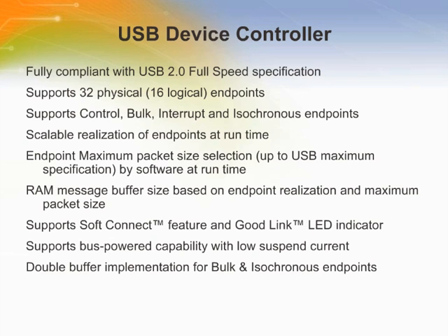The USB is a 4-wire bus that supports communication between a host and a number of peripherals. The host controller allocates the USB bandwidth to attached devices through a token-based protocol. The bus supports hot plugging, unplugging, and dynamic configuration of the devices. All transactions are initiated by the host controller.